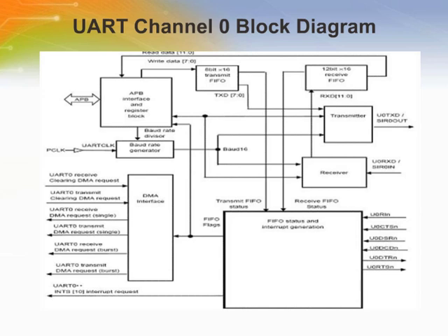Here we explain about the UART functionalities. The device has a baud rate generator, transmit first in, first out, receive first in, first out, transmit logic, receive logic, interrupt generation logic, interrupt timing, UART interrupt block, DMA interface, IrDA circuit description, hardware flow control blocks as shown above. A few of them are explained below.